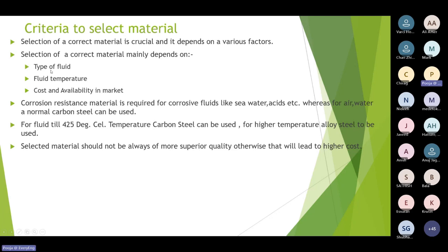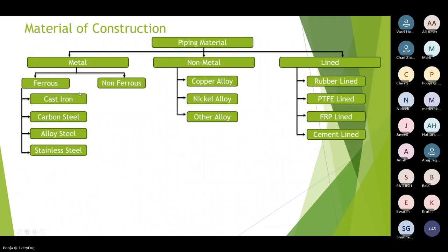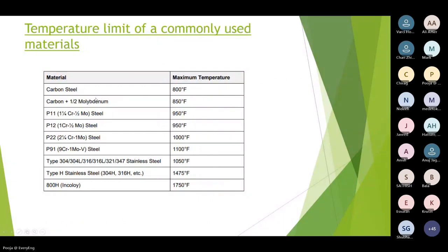If it is normal water, you can go for carbon steel also. But if some fluid is very highly corrosive, then you cannot go for carbon steel. You have to go for stainless steel. Then also the fluid temperature. This slide will help you.